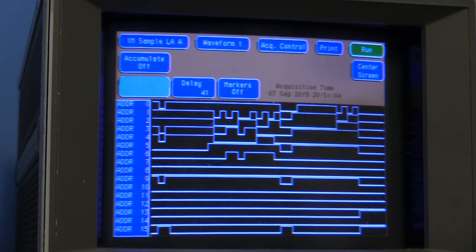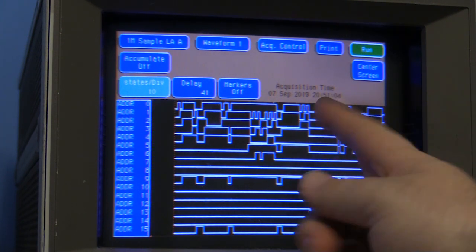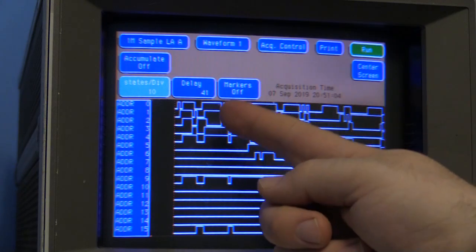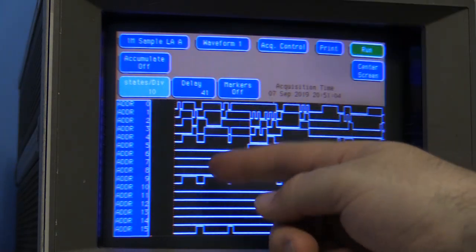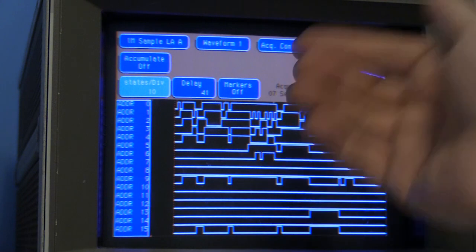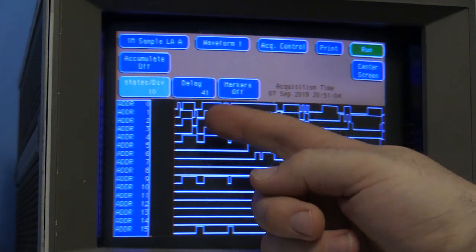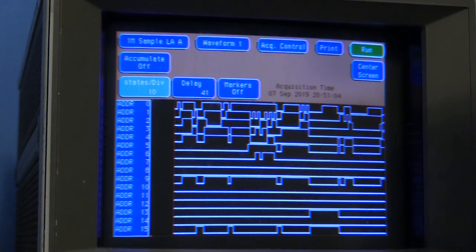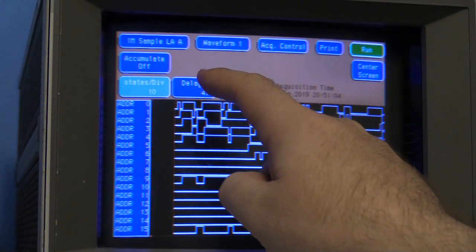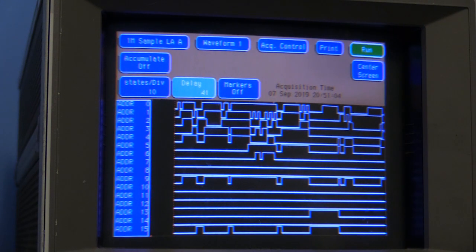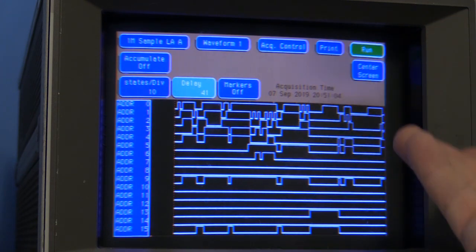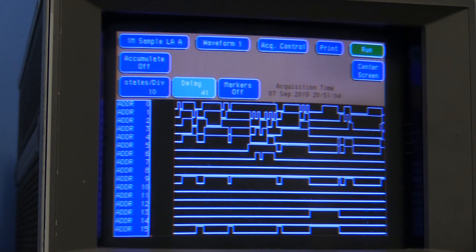Let me go ahead and zoom those in a little bit. So you can see over time, as different address lines get held high, that's how it comes up with a hexadecimal address of knowing which memory address to read, based on the zeros and ones that each of these are set to at any given point. So I think what we're going to find on the bad Sega CD is that some of these lines that should be showing activity aren't going to be showing activity, and that's going to be why it's setting bad addresses, then reading incorrect code and crashing.